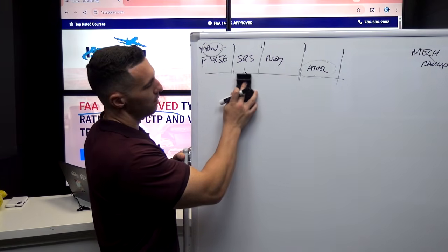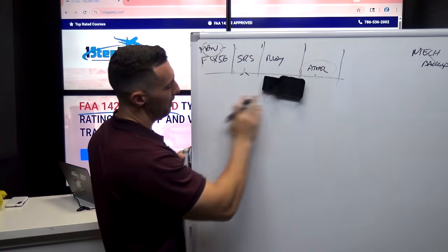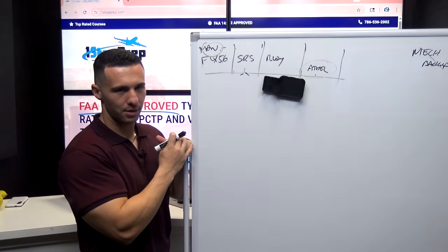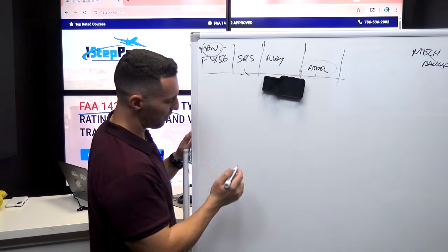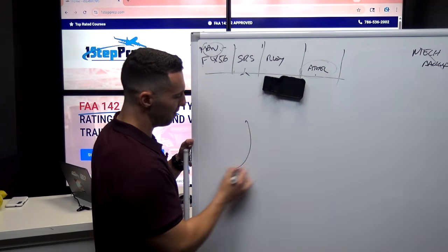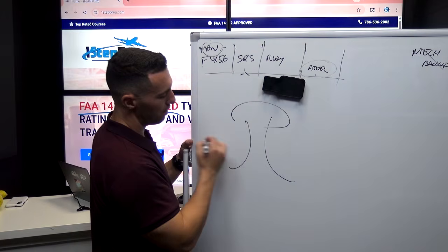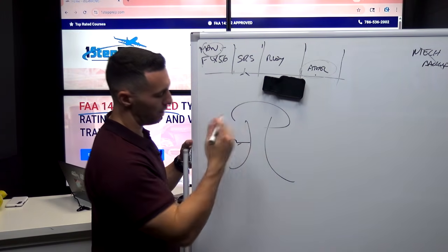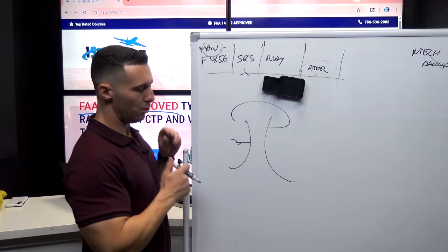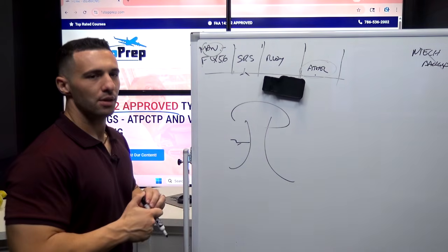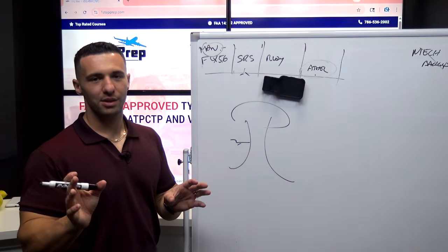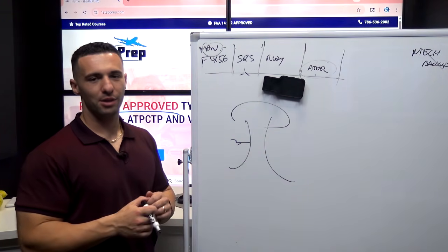Windshear is one of these things that is not won by a function of airspeed, it's won by a function of angle of attack. I just want you guys to be real clear on this. If this is your microburst, and you're coming up to it, and you get Windshear TOGA, and you start pitching into the flight director. If the autopilot's engaged, leave it engaged. That's a beautiful thing about this machine. The autopilot fights the Windshear.